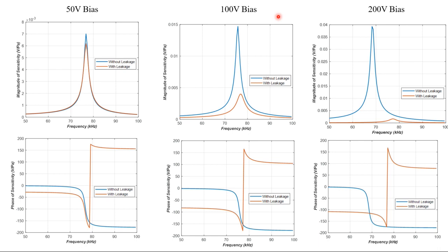So besides higher electromechanical conversion ratios, you're going to have more change in capacitance. As a receiver, the CMUT is going to have more, because a very thin gap remains between the silicon and the glass. So for incoming ultrasound or mechanical disturbance, you're going to have a very large current at the output, or voltage for that purpose. So the sensitivity is going to improve.